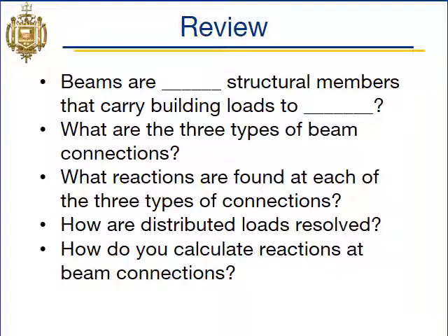Remember, at a fixed connection, we have a reaction force in the X direction, a reaction force in the Y direction, and a reaction moment. That's our fixed. Our pin only resists forces in the X and Y direction, and our roller resists only one force, typically in the Y direction.